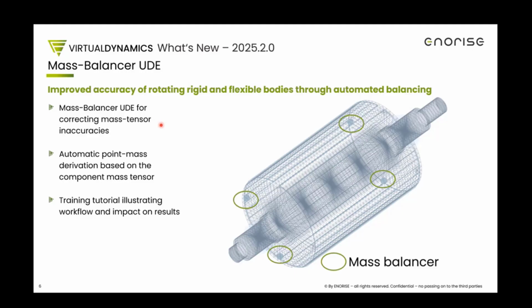This was a trap which we actually noticed many users falling into, unknowingly having an imbalanced system. I have personally seen an extreme case of, for example, a 6-cylinder crank train displaying a very unexpected 2.5 order excitation due to this kind of imbalance in the system, right?